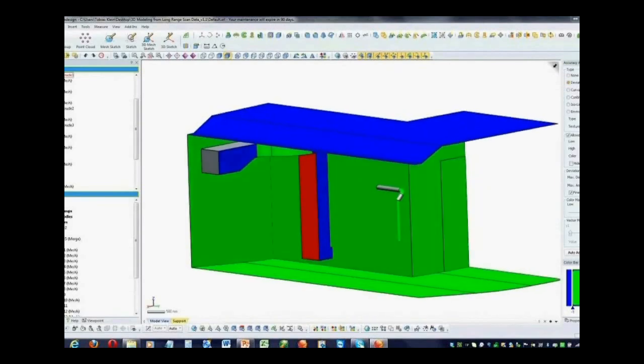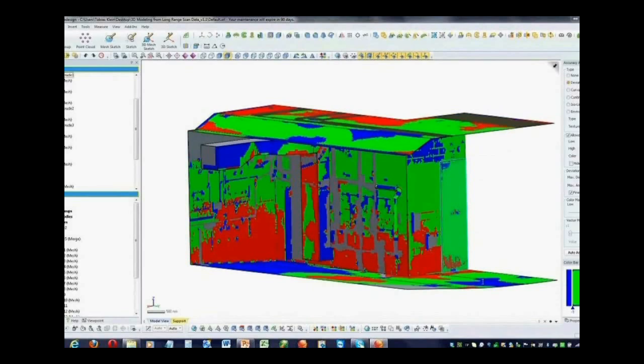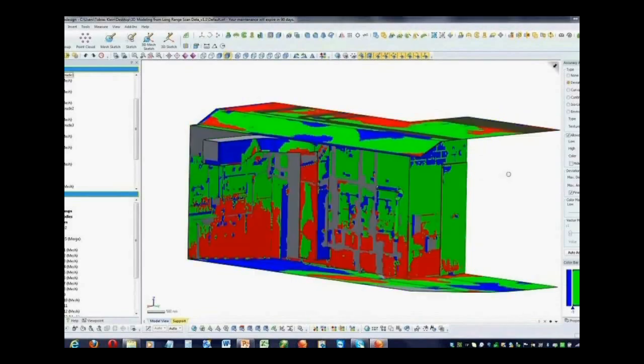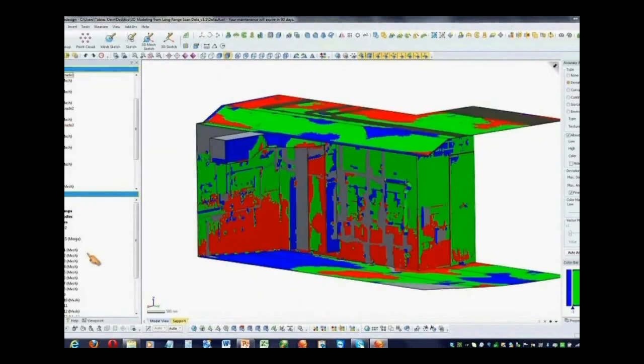Okay, Danny Celis asked, can we separate the object with layers? Actually, we don't have layers, but in Rapidform we have a model tree and we have a feature tree. The feature tree is our timeline, where every modeling feature comes after each other and has dependencies to the parent feature and to the child feature. And in the model tree, we have a categoric listing of each feature, of each object.